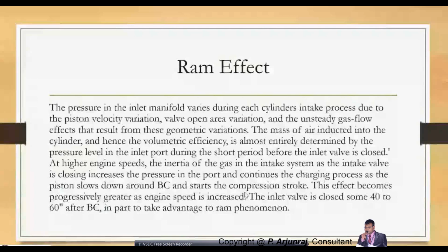So what is the advantage of this effect called the RAM effect? It's not that it is going to have a high influence on the volumetric efficiency. It will have, but I told you, you have the inlet valve opening and inlet valve closing with respect to the valve timing diagram you've seen. The inlet valve is going to get closed somewhere 40 to 60 degrees after bottom dead center.